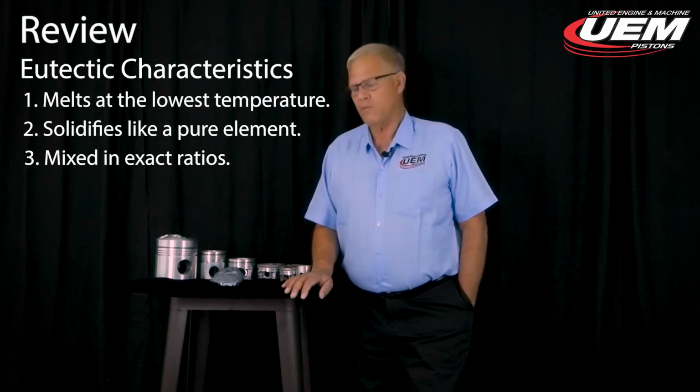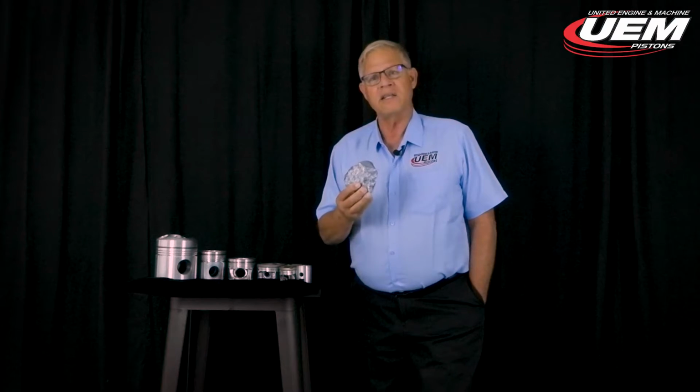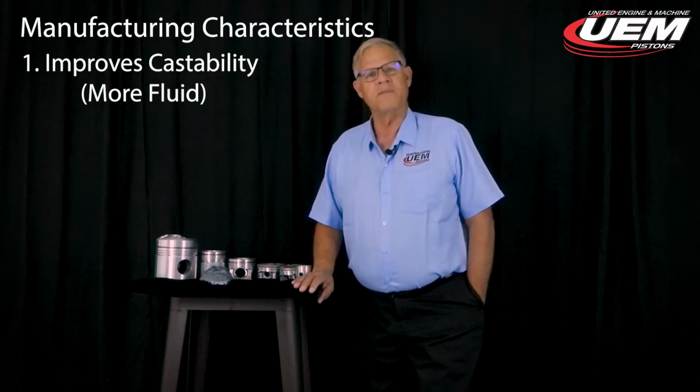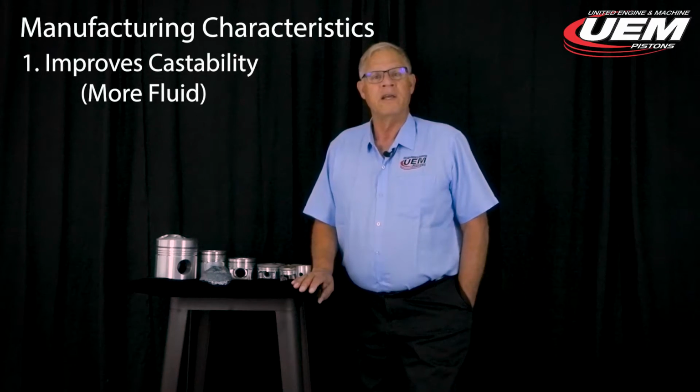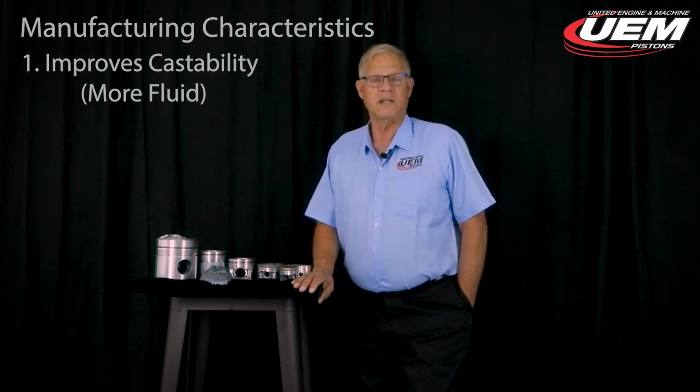So again, we're talking about the addition of silicon, and there are reasons that silicon is used in aluminum alloys. Let's cover a few of those reasons, and it'll give you an idea why we use it. First off is more of a manufacturing condition: when we mix silicon with aluminum, it improves its castability. It improves its fluidity, and you get very, very nice castings out of a silicon alloy.